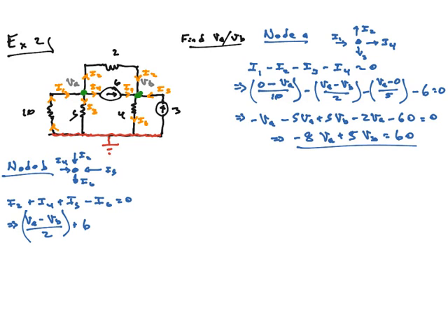I5. We know I5. That's the 3 amp source, so that's good. 3. I6, we don't know. He's leaving, so he's minus. We start at B, and we go to the ground, divided by 4 is his resistor. So there's his equation. Again, two unknowns, A and B.